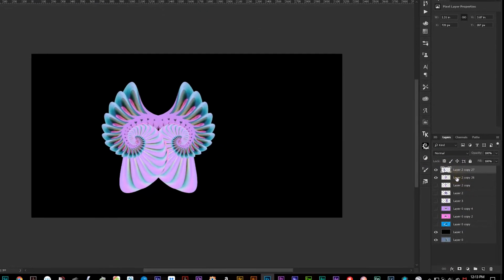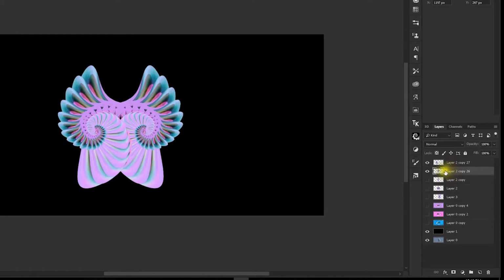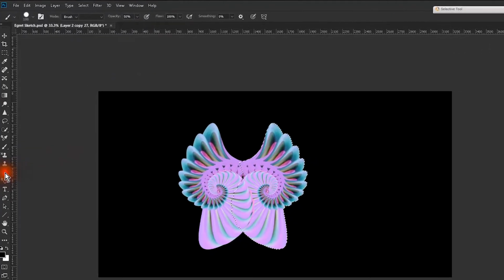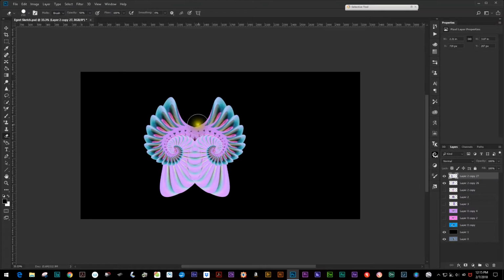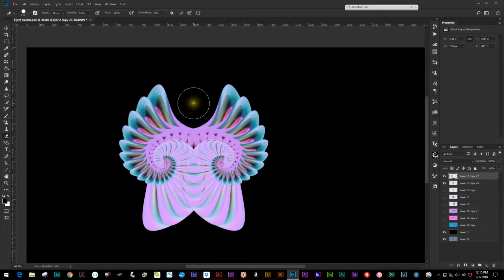I'm going to the bottom of the two layers, and with a Control click, left mouse click on that layer, I've now selected the component on that layer. I will now go to the top layer, and I'm going to erase at 50% just the intersection point. Hold the left mouse button down continuously. Do not let it up, because you'll apply 50% twice. What I want to do is see through the top layer to the bottom layer with both at 50% visibility. Now that I'm happy with that, I'll go back and deselect that selection on the layer,